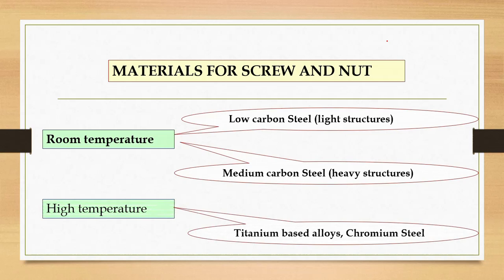But if you use the bolts that are actually at high temperature, they are generally used in engine assembly, like in crank assemblies, or where there's a very high temperature. So we use titanium as alloy, or chromium, or manganese. So these are expensive. Yes, if you want to buy a bolt that is used in the crank assembly, the bolt set costs about 12 or 1300 rupees.